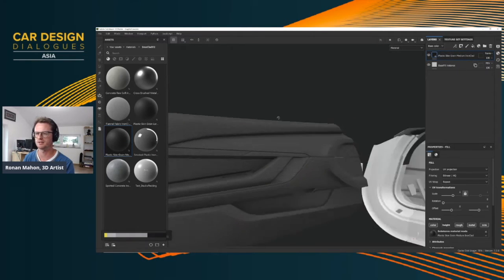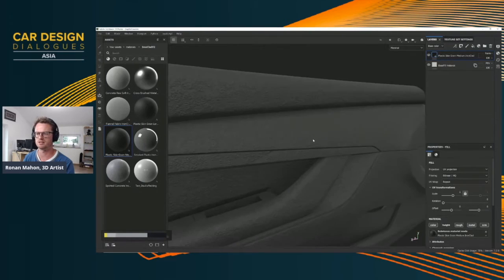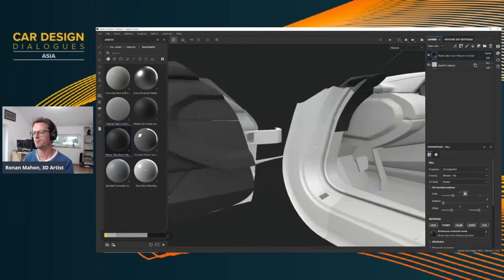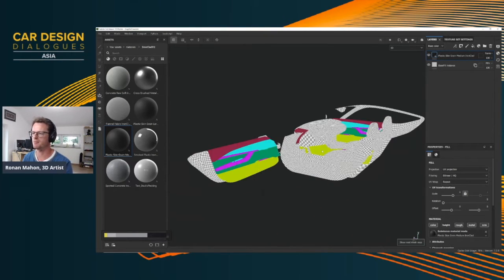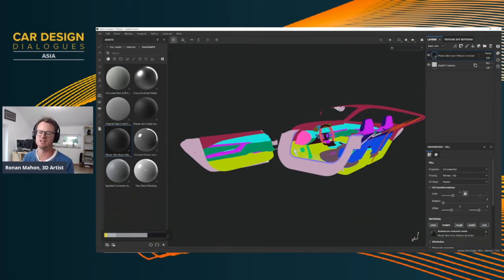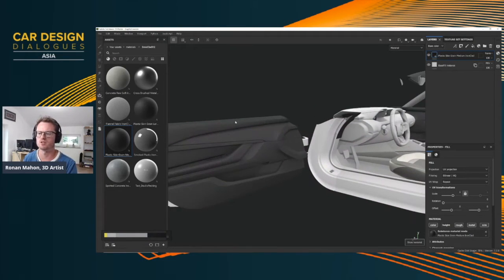This is my layer stack on the top right, and you can see there it's applied to the entire door. Now, one thing to say, and maybe a little tip for starting out, beforehand, I set up what's called an ID map, which is set up in your 3D program, and in it you can sort of designate different areas of material. So I can say here, I think the dash and the side of this trim are going to run together. We're going to share this bottom material. It may be across different surfaces. But this is just a really quick way for me to block out in 3D before I've even started. It's not to say that I can't change my mind later. This is a really good tip for speeding up your workflow.